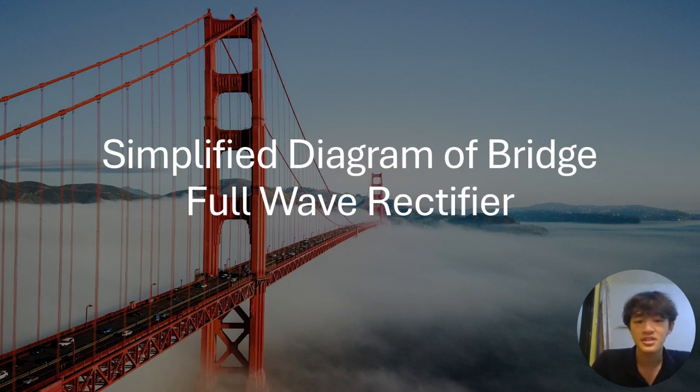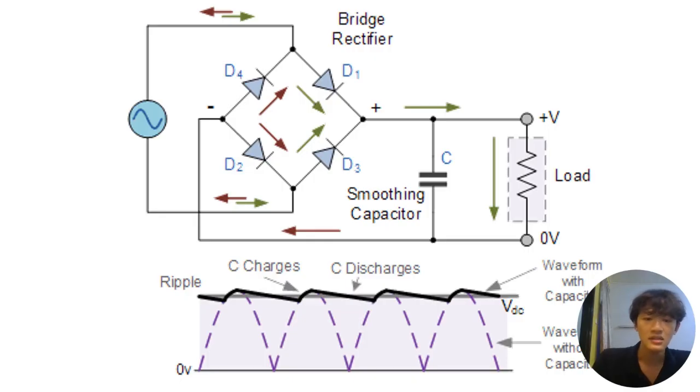Here is the simplified diagram of the bridge full-wave rectifier. As you can see, there are two directions of current flow. The green line is when the current is flowing in one direction, and the red line is when the current is flowing in the other direction. You can see there is ripple here, and then there is a chart. When the voltage is decreasing, the capacitor, when fully charged, will provide the voltage for the circuit. As the voltage increases again, the capacitor will be charged again, and the process repeats.